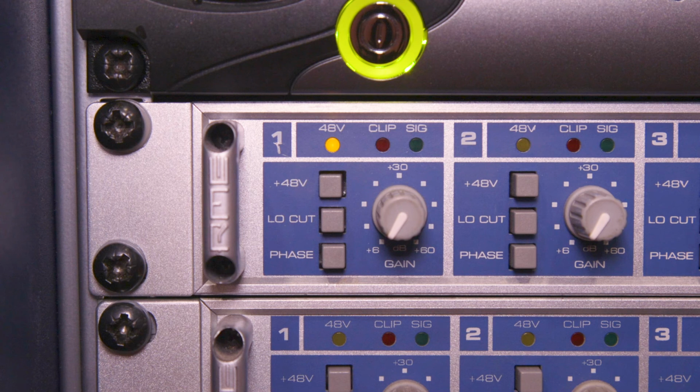Dynamic and ribbon microphones do not need phantom power. If switched on when using a dynamic microphone, it usually doesn't do any harm. But you must be very careful when working with ribbon microphones, as the phantom power can cause the ribbon in the microphone to burn like a filament in a light bulb. Only use phantom power on non-condenser microphones if their instructions tell you to do so.